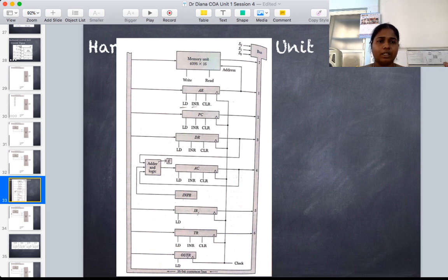So in clock cycle 2, the data from the memory unit is put inside the common bus. And in clock cycle 3, the data which is in the common bus has to be received by the accumulator. In that case, the load signal of the accumulator is raised high during the third clock cycle, and it receives whatever data is there in the bus structure.